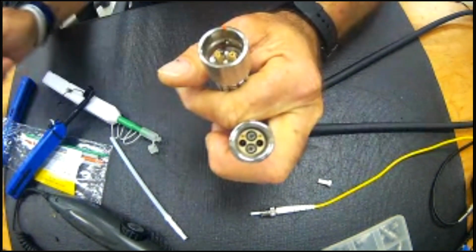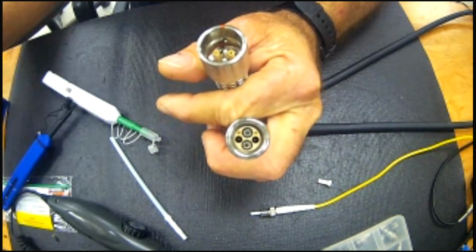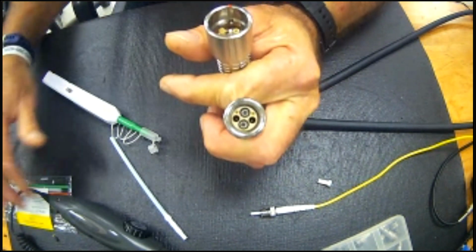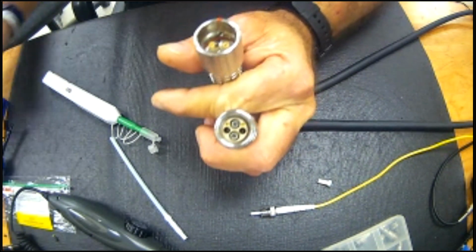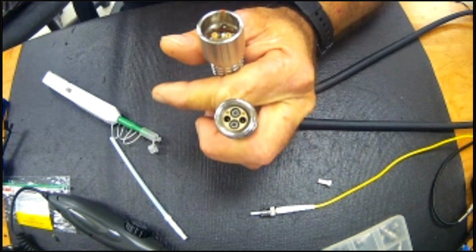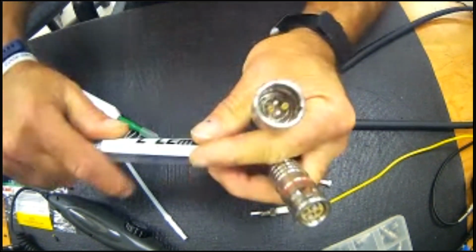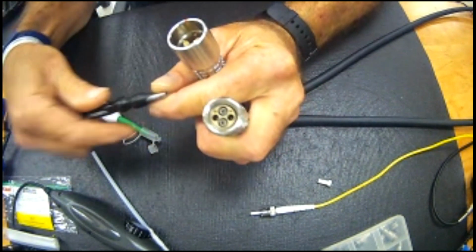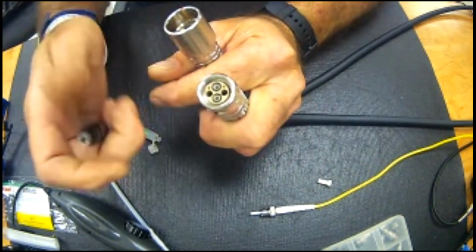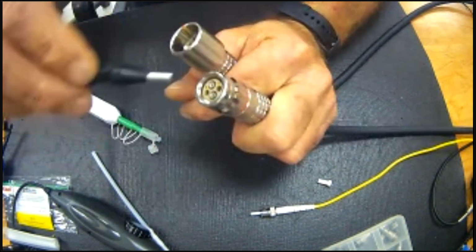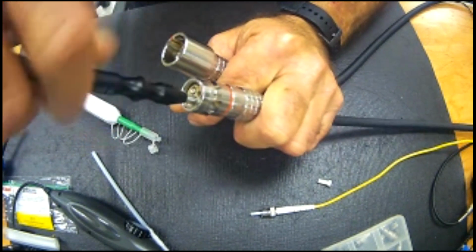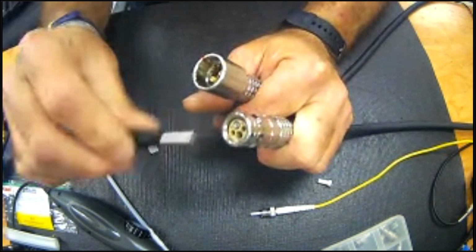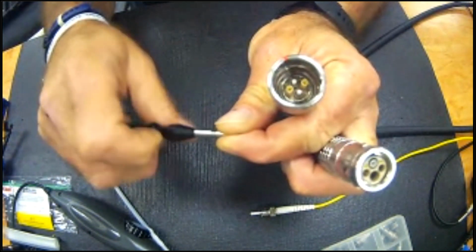Now, the plug, having the alignment sleeves, would require that you own a special tool to remove that alignment sleeve. That actually exists with every connector, whether it's a mil-tac or multi-pin connector. You have to own something to remove alignment sleeves. In this case, it's relatively inexpensive. The inside of the alignment sleeve is threaded. This is a threaded tool. It simply goes down over the alignment sleeve. You thread it on 3 or 4 threads and you're good, and you pull. You've extracted the alignment sleeve.